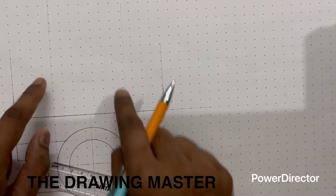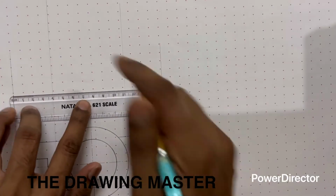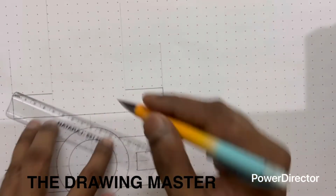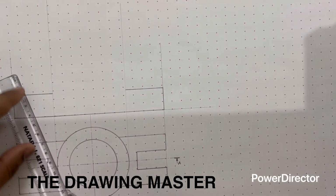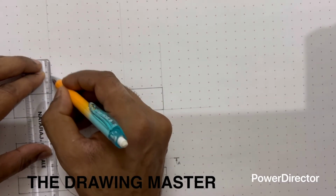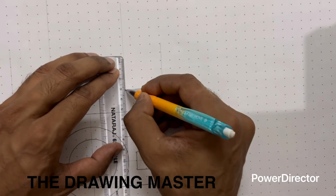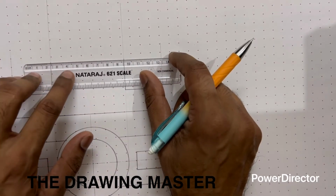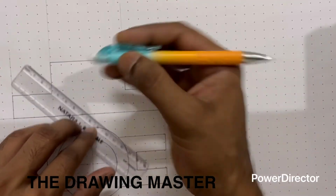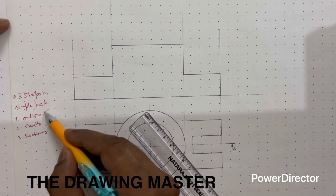Now this is the projection for the cylinder. So we have to draw a horizontal line up to that cylinder. This is for the base. Now from here the cylinder will start. So this height is 30. Now here the cylinder will close. So just check this. This is the outline of the object.